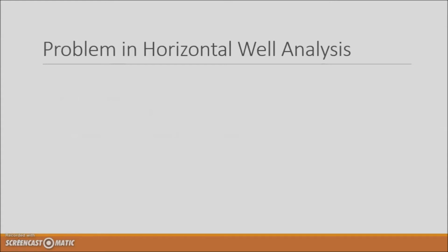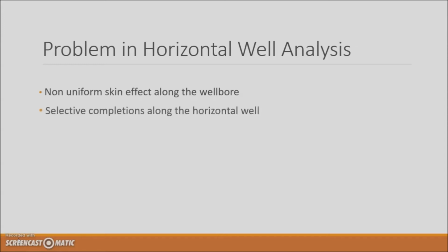However, there are a few problems in horizontal well analysis. Factors that complicate horizontal well test interpretation are the non-uniform skin effect along the wellbore, selective completion along the horizontal well, and the heterogeneities in the vertical direction as well as the lateral direction.